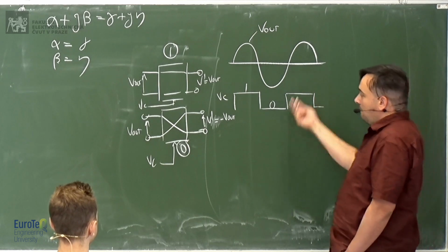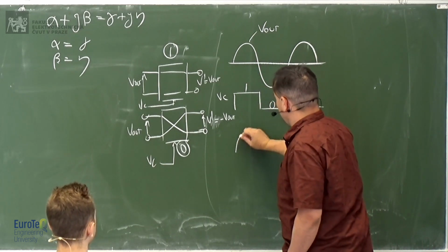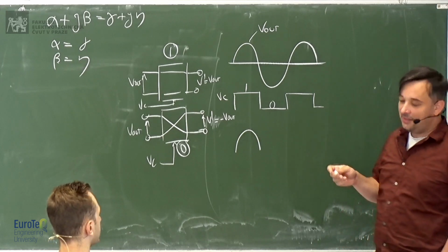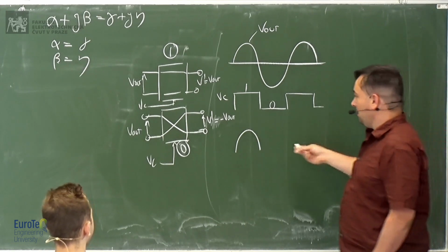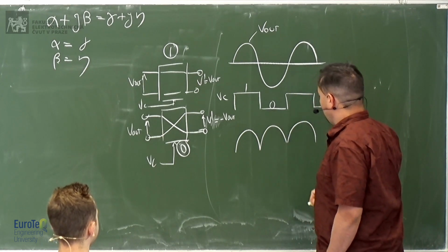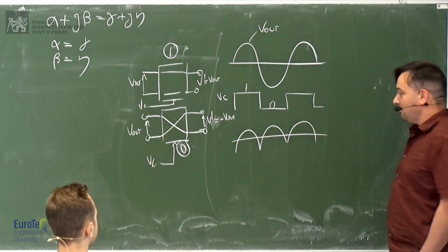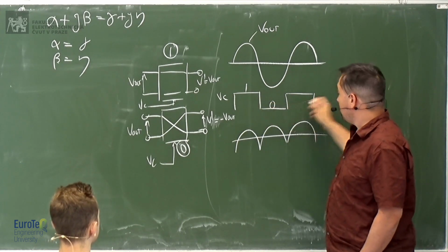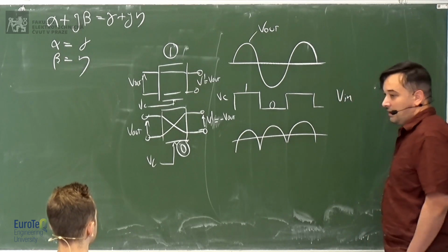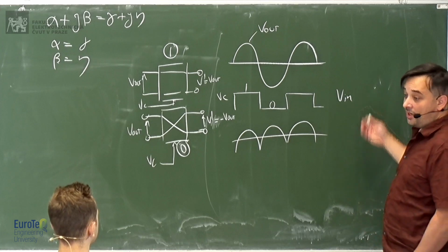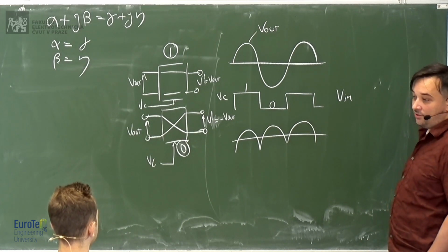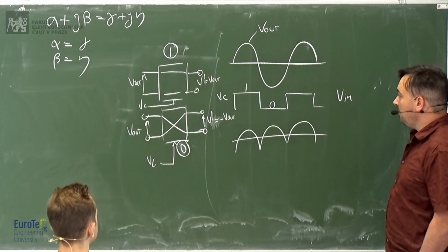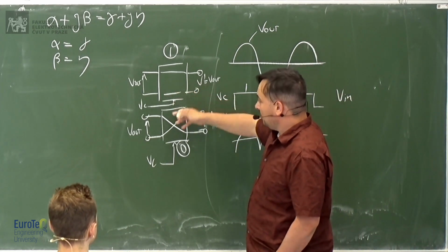And then we apply what we've seen here. So here we have... this will rectify it. In this case, it's a rectifier, but it's a controlled, phase-controlled rectifier, which can be used to demodulate. Okay? So then you take a low-pass filter and you get the average, okay? Now, if this control voltage keeps the same, this control voltage comes from the input voltage. You can take the input voltage and you can square it using an operational amplifier, a comparator, and simply you can flip with the same frequency.